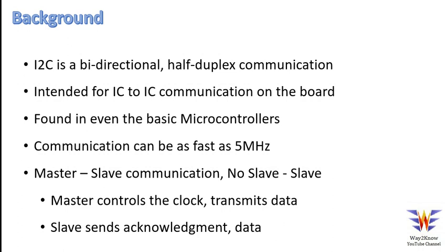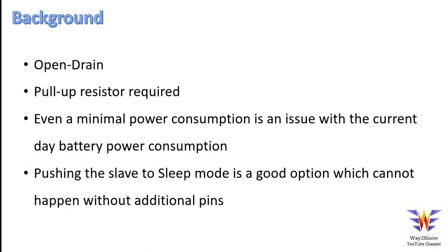One of the important terminologies in I2C is master-slave communication, where there will be a master and then there will be a slave, and the master initiates everything to the slave, and then the slave responds as per the information requested by the master. There is no slave to slave communication, only the master would be present. So we can say that mainly the master is the guy who is in control of the things.